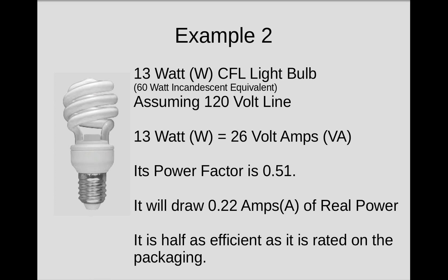So we're going to make the same assumptions that you have 120 volt service. This bulb on the package says 13 watts. If anybody notices out to the right, the volt amps on this bulb are 26 volt amps.